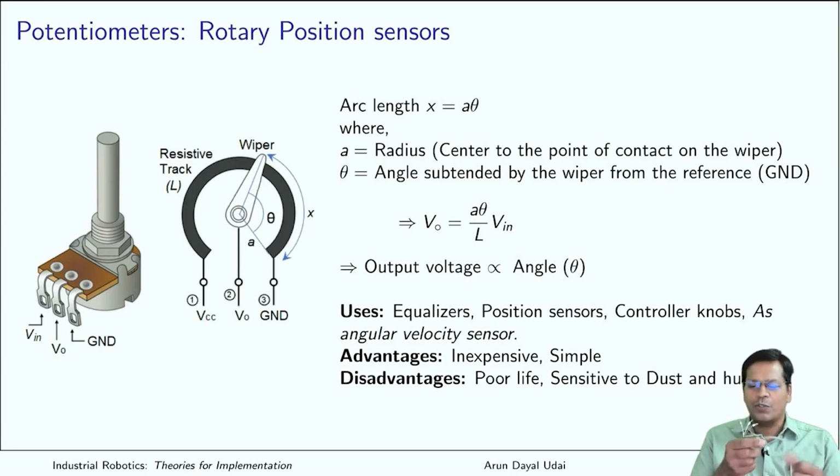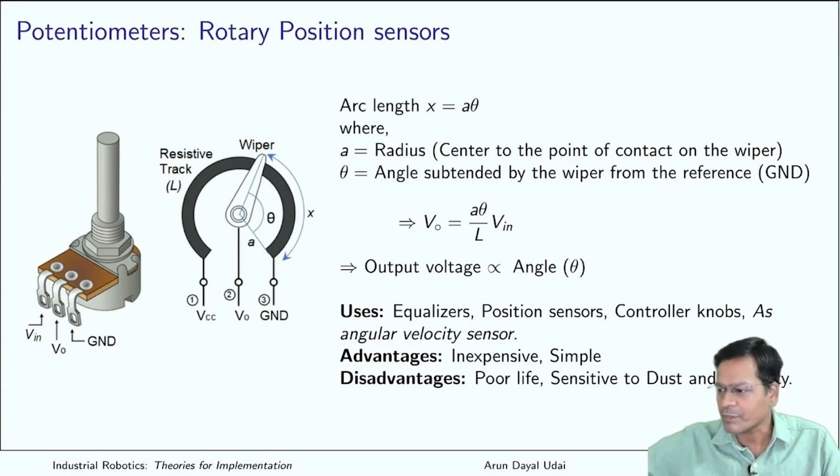In case of an optical encoder, it was 5 wires: one is casing ground, and then voltage, ground, and phase A, phase B. Sometimes index is also there. So it may have 5 or 4 wires, but this always has 3 or 4 wires because of this shielding ground.